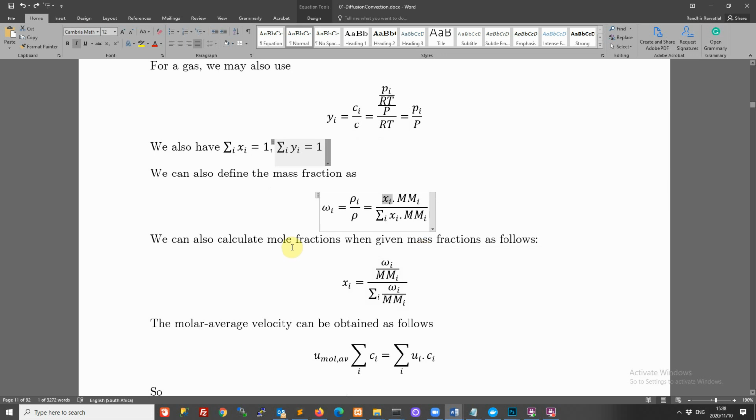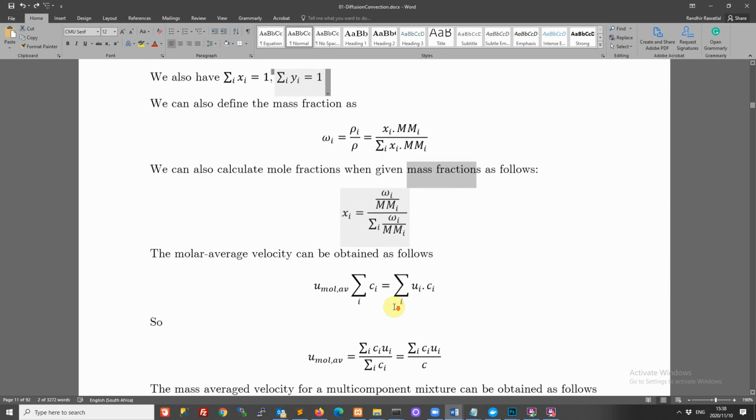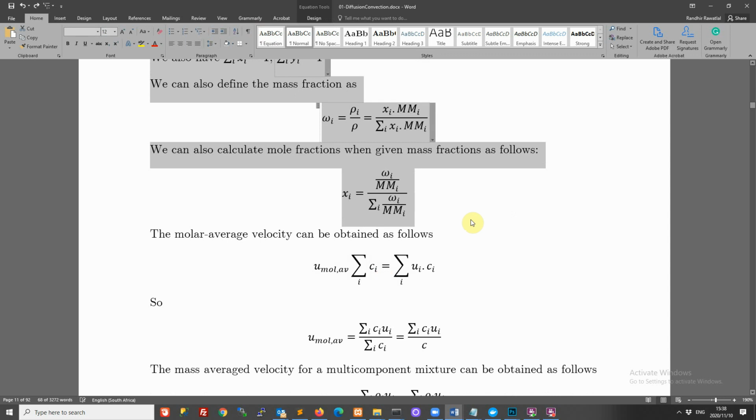If you wanted the mole fraction and you were given the mass fraction, right? So in this case, we were given mole fractions and we wanted mass fraction. If we had the reverse, if we wanted mole fractions from mass fractions, then again, you take a 1 kg basis. So all components add up to 1 kg. So the mass of component I is omega I. And then if you divide mass by molar mass, you get number of moles. So that's the moles of component I, and divided by the total number of moles, that gives you the molar fraction. Okay, so in a way, these are just reminders. I expect that you do know all these things anyway.